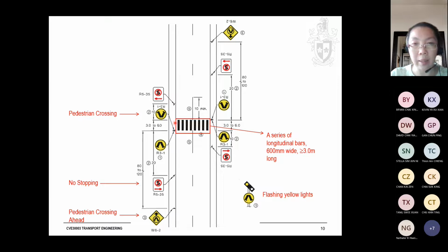And these longitudinal bars here are 3 meters long, that's the minimum. Now, if there are a lot of pedestrians, we could extend them beyond the 3 meters.